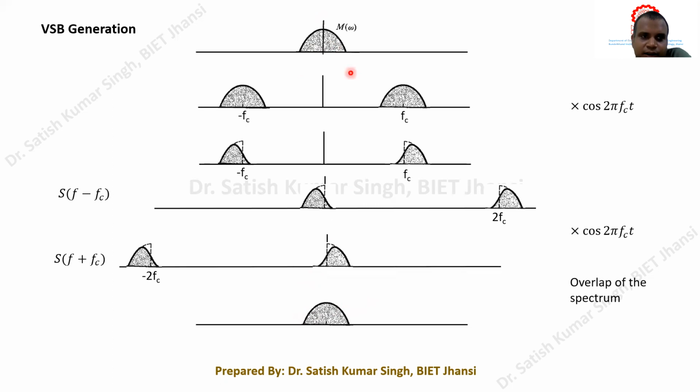So how do we get that? We have to look at it. After passing the signal through a low pass filter, the other high frequency components will be eliminated, and the reconstructed signal will be our message signal. So we have to look at how this overlap should be done, so that our demodulated signal will be our original message signal.